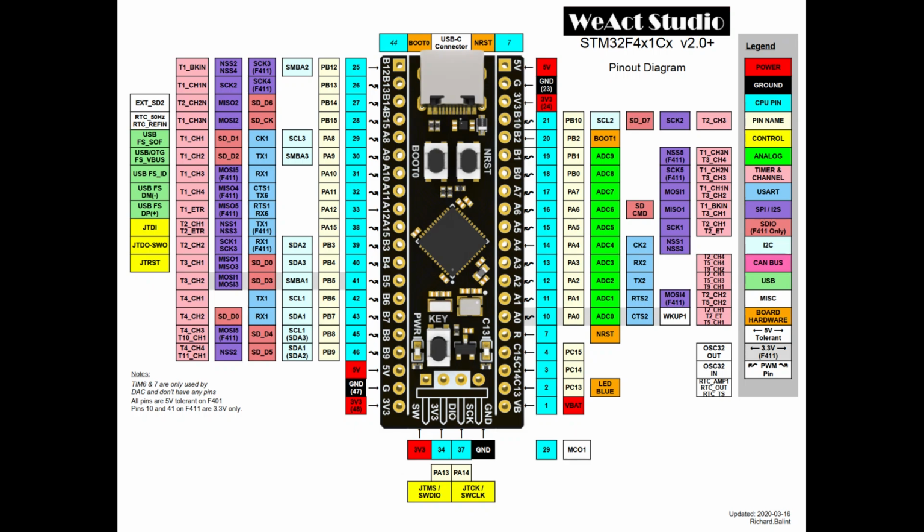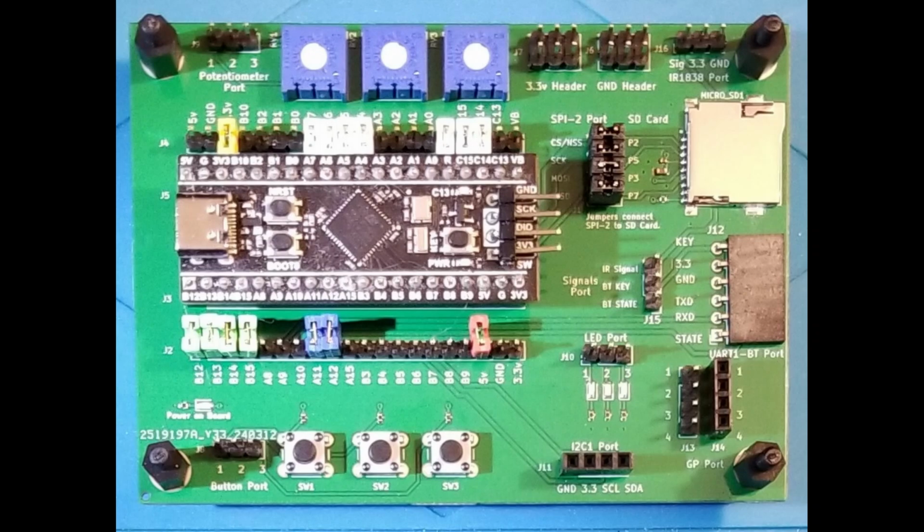The BlackPill schematic shows that most pins depicted with the squiggly arrow permit PWM signals. The two code examples today utilize an LED, but we can use the same ideas on, say, an L298 motor controller to control the speed of several TT motors on a robot car.